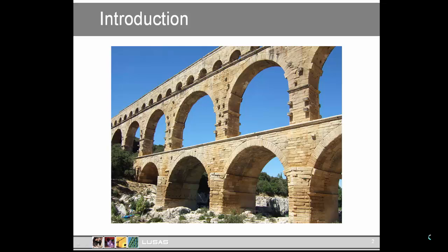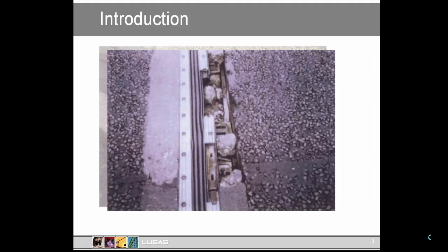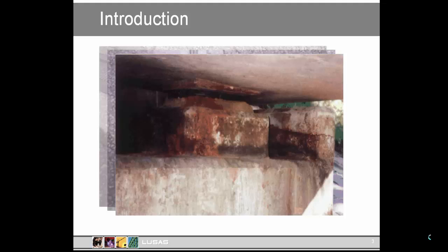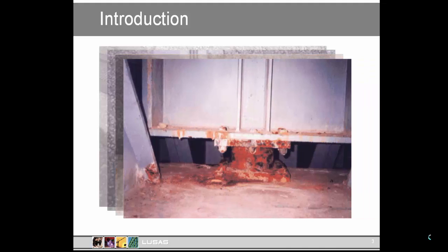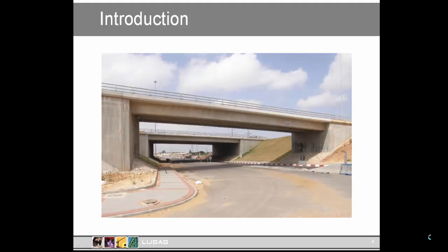Instead, often we go out on bridge inspections and perhaps you have a sorry collection of photos like these: damaged joints, and underneath, bearings and girders suffering because of water leaking through, and depending on the climate, probably with de-icing salts as well. So around the world now we tend to build jointless bridges.